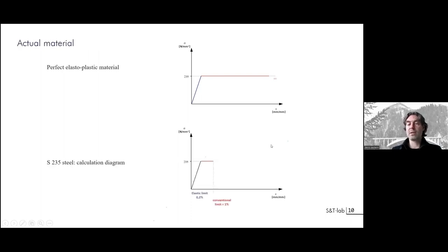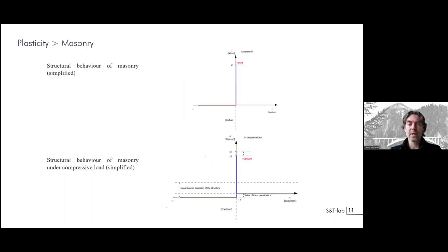You see that this plastic zone is limited, so you will need to be close to some extent to elastic behavior. And if you don't do it that way, you will suffer cracks or large deformation in your system before the loading can be sustained.